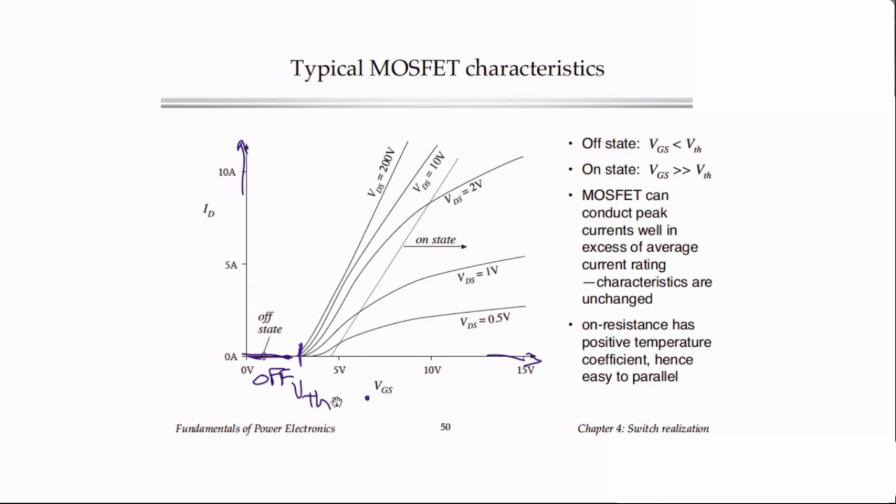And the gate driver has to bring the gate to source voltage higher than the threshold voltage to turn the MOSFET on. So here, as you can see, as we raise the voltage above the threshold for the first few volts, the MOSFET starts to turn on, and when it's up here, maybe 10 or 15 volts, the MOSFET is all the way on.